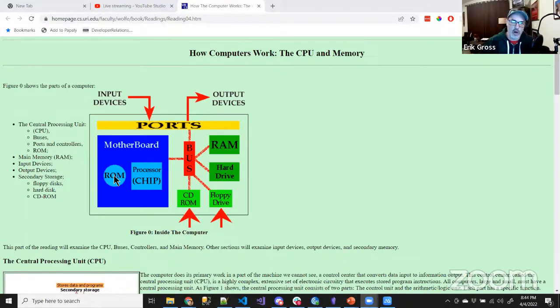And the way it works is in this ROM, there is a tiny computer program. And the very first instruction of that computer program is literally coded mechanically into the chip. When the chip first receives power and starts its very first fetch, decode, and execute machine cycle, already built into that address register is the physical location over here in ROM of the very first instruction.